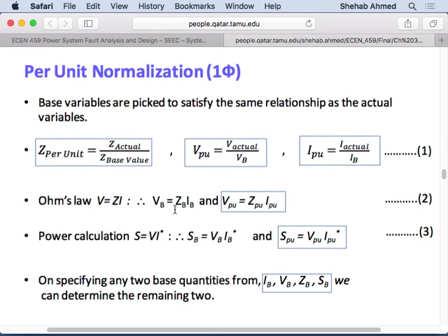So now I have a voltage base, impedance base, current base, and power base: base quantities for all 4 physical quantities in a power system. Then you convert all impedances and all voltages to per unit values. And we will have to do that every time we see a transformer.